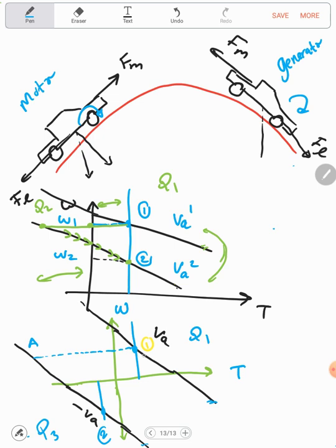So you can see that the machine is generating huge braking torque. Actually, this is the braking torque, T braking. After that, the machine will decelerate. Here it will cross zero. Now, if at this point we disconnect the load and engage a mechanical drum, the machine will stop here.